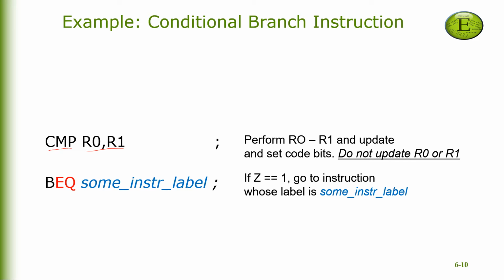The compare instruction only performs a subtraction operation, except that the result of subtraction is not stored in either register or the operands. However, what it does is only update the code bits, set or reset.